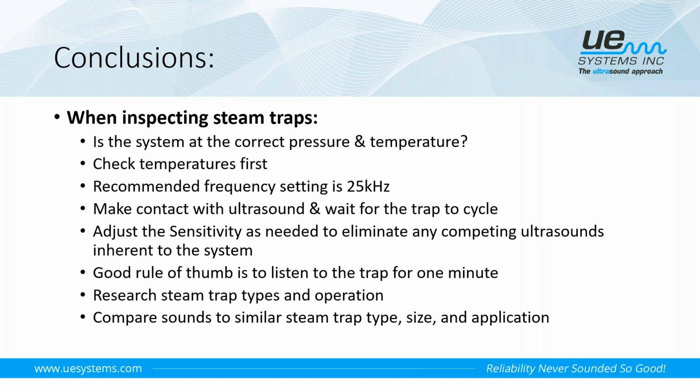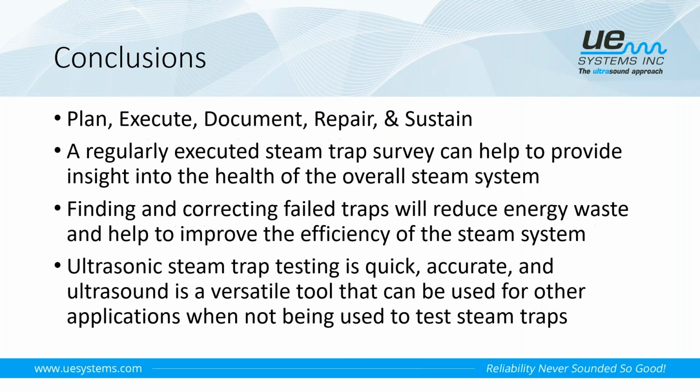A lot initially with ultrasound is going to be about comparison. So before you ever begin the survey, if you have your ultrasound instrument, you got your UltraProbe, just go out and start listening to steam traps to kind of get an idea as to what they should and shouldn't sound like. And that will certainly help you out a lot once you actually do your steam trap survey.